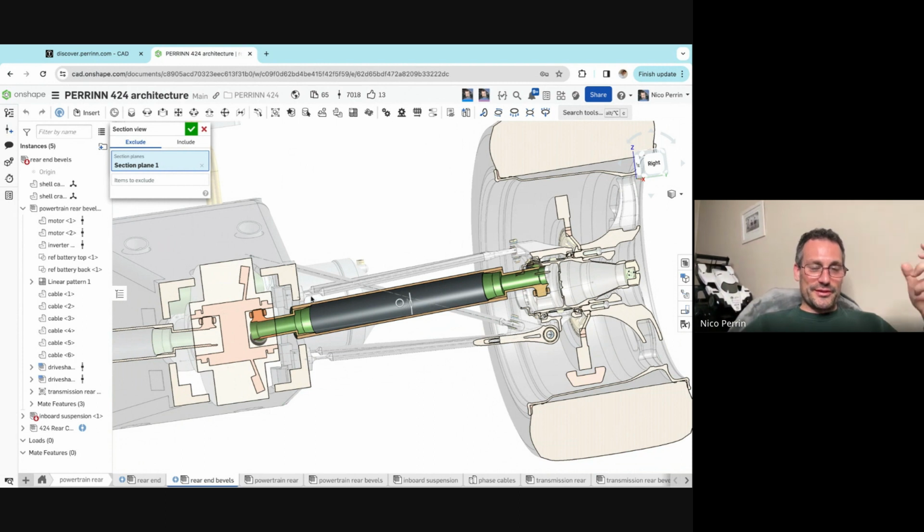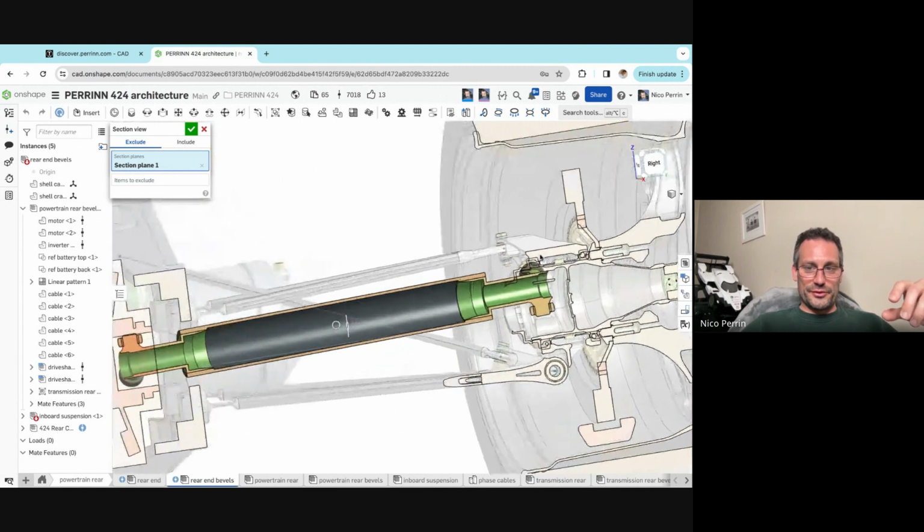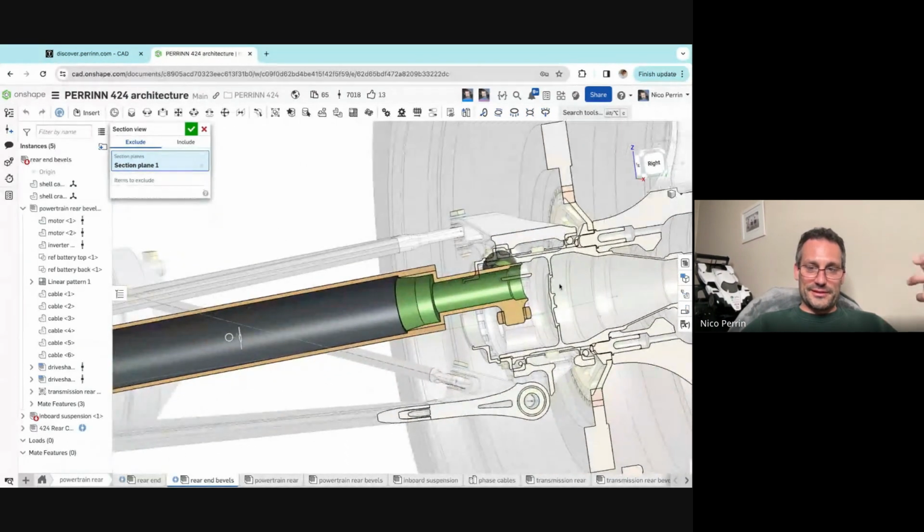The suspension, for example: we had a very detailed suspension with all the bolts and mounting for the LMP1. But with Isla 2 years ago, we rebuilt a completely new model, which you see on screen now. The axle is still the LMP1, but the upright is new. And because I wanted a new kinematic model last year, I've rebuilt a completely new model that's not as detailed, but contains better information for location and aerodynamics.